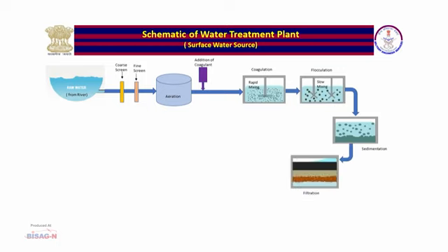Filtration is a process for separating suspended and colloidal impurities from water by passing through a porous medium or porous media. Filtration is employed to effectively remove turbidity, color, microorganisms, precipitated hardness from chemically softened waters, and precipitated iron and manganese from aerated waters. Filters can be classified according to various parameters. Based on direction of flow, they can be downflow, upflow, biflow, radial flow and horizontal flow filters.